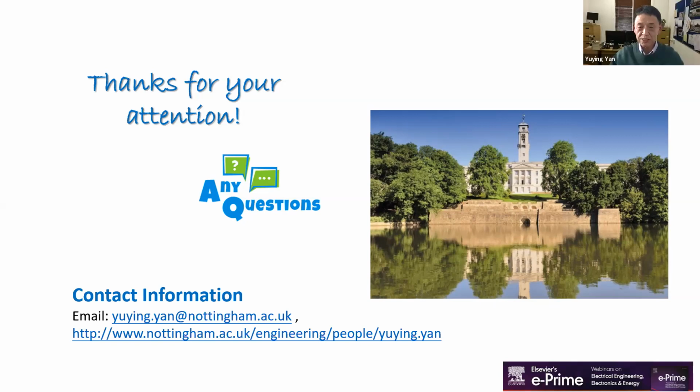I say the battery is like a human. It has an optimum operating temperature, like 25 to 40 degrees C. We need to control the temperature, not too high, not too low, like a human body. Many methods can do the job, but we can't use water to directly cool the battery. You can use microchannels, but we need to think about vibration, discharge and many things. Heat pipes are very good, but they increase the weight.